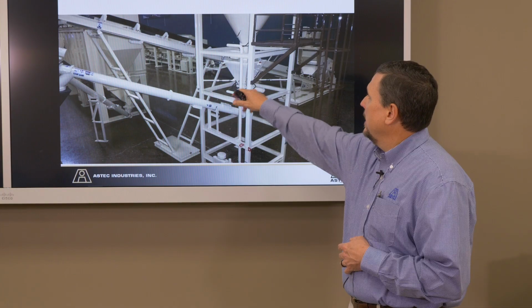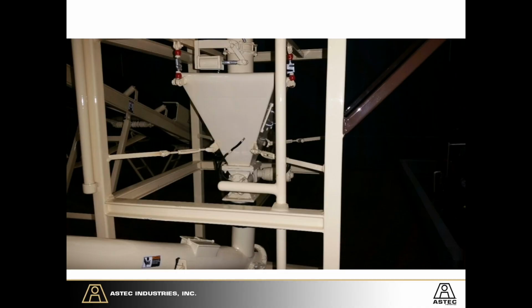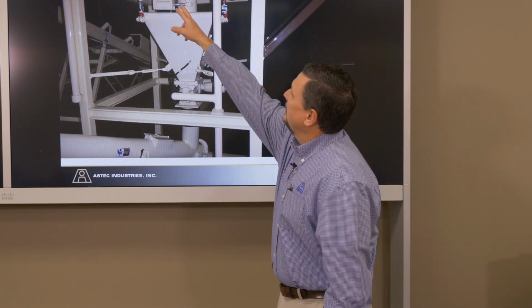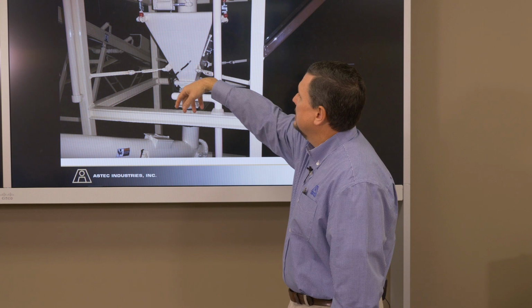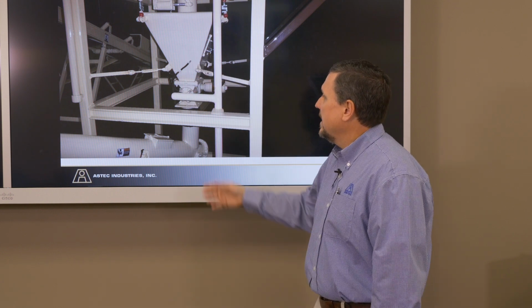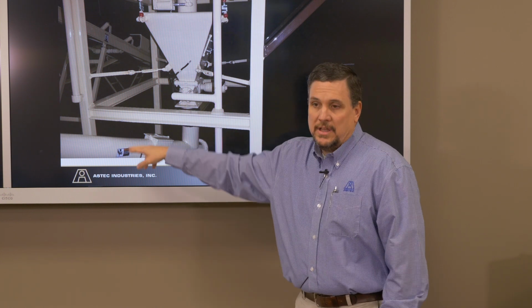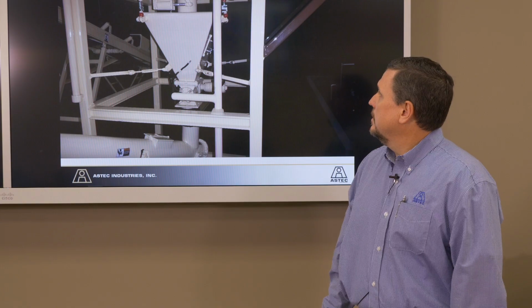And you can see here, this is what we have on a weigh pot. Now, not only are weigh pots pretty popular, and probably that's what you see on most mineral filler systems, but there are impact plates and a few other devices that are used to meter dust. They are weighing devices too. So if you can use that, that is the best way to look at the weight of mineral filler. If you look at this mineral filler system, there's a butterfly valve here at the top, which opens and discharges the mineral filler into the weigh pot. You would take a weight here, and then the airlock is turning here, discharging it into the drum and introducing it into that screw for the drum.